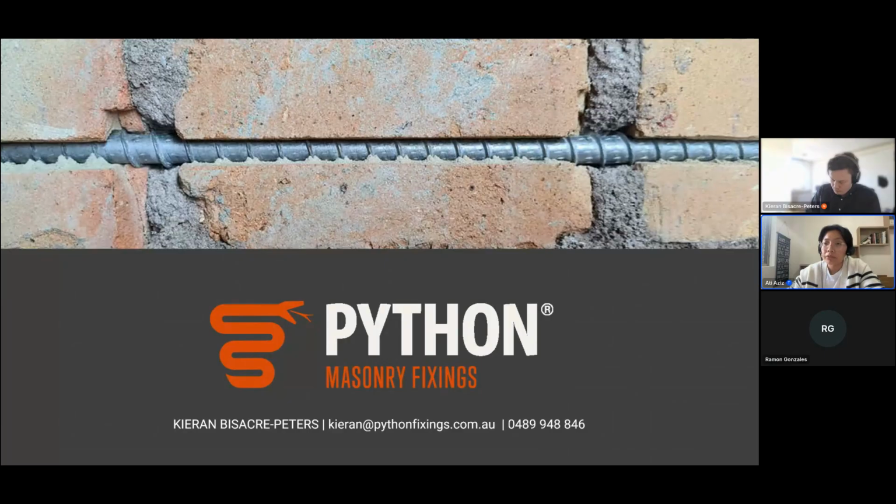All right, cool. The next question I've got is from Michael. Do you think Australia might introduce a mandatory wire tie inspection like the US someday? I think that's quite possible, given how many of these buildings we come across that do have corroded cavity ties. Although there are triggers in which they do get remediated. Obviously, if you're doing upgrades to the building, remediating or retrofitting it, especially over 50% in Victoria. So I wouldn't be surprised if that came in at some point in the future.